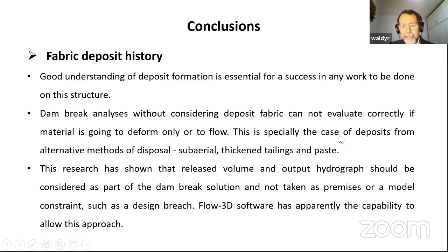My conclusions are in three aspects. First of all, I hope I can convince you that a good understanding of deposit formation is essential for any work that you try to do with the tailings deposits. If you're going to build something on tailings deposits, or if you're going to do a study like this of dambreak, take the time to try to understand your deposit before you do something.